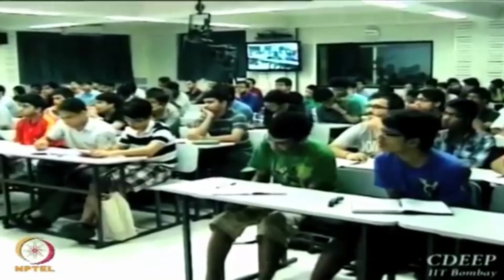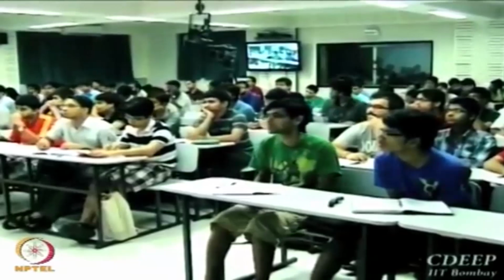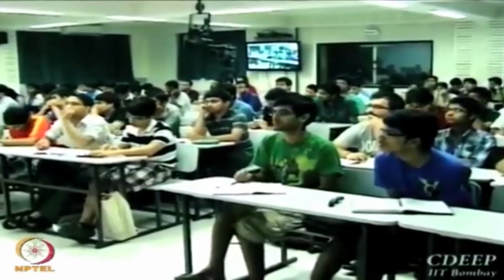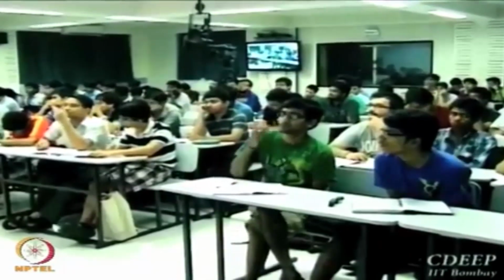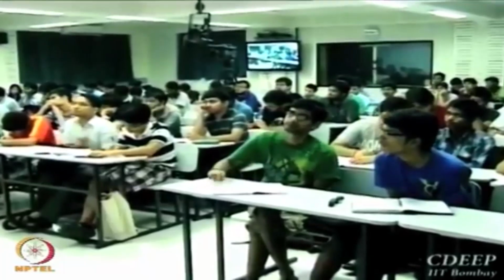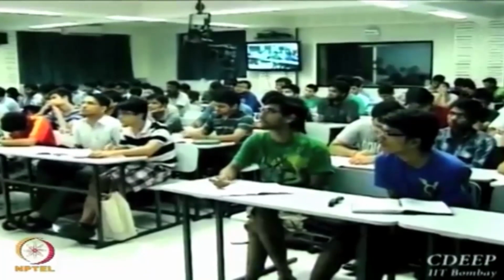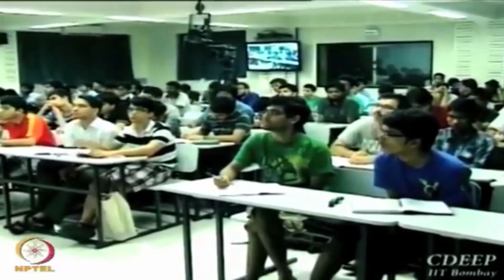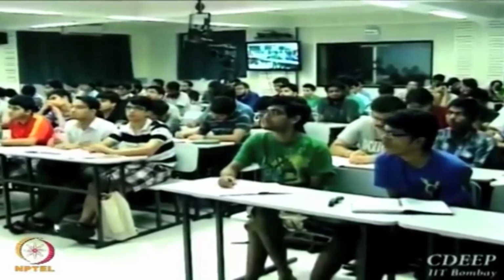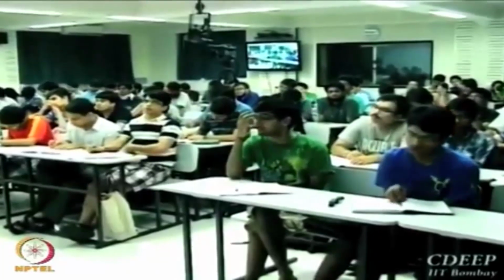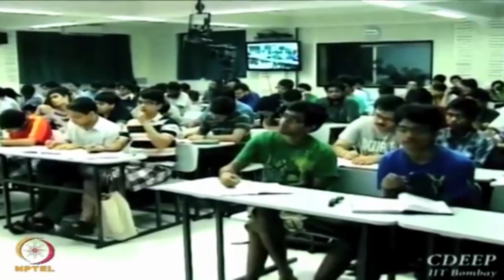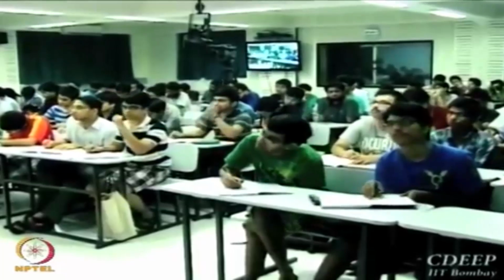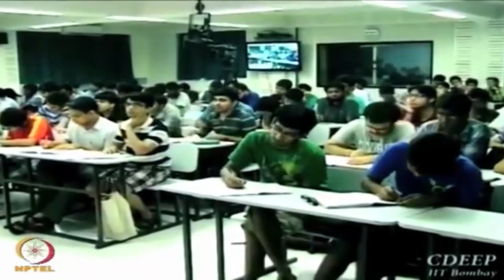So based on negative feedback and a simple current mirror, probably we can improve some of the sensitivity issues, and two such most popular current mirrors which are available, one is called the Wilson mirror, the other is called the regulated cascode. Okay. Both use negative feedback in their circuits. Just now I said it, and now here is that circuit.